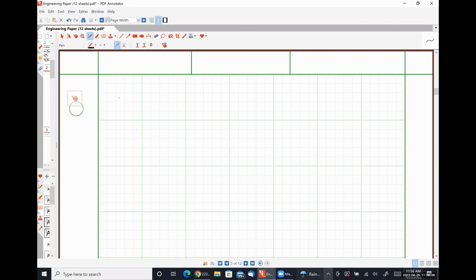I'm going to generalize an expression for multiple sinusoidal frequencies, okay? Let's say that we have a waveform, V of t, is, I'm going to call it Vm naught cosine omega naught t plus theta v naught, plus Vm1 cosine omega 1 t plus theta v1, all the way out to Vmn cosine omega n t plus theta vn. So this could be the sum of an infinite number of sinusoids. As long as the omegas work out in such a way that this is a periodic function, what I'm about to show you applies.